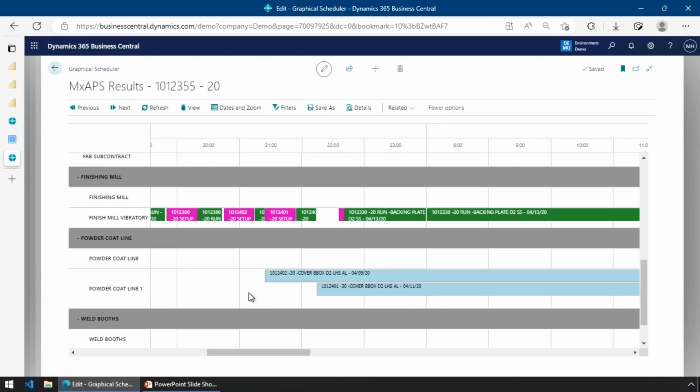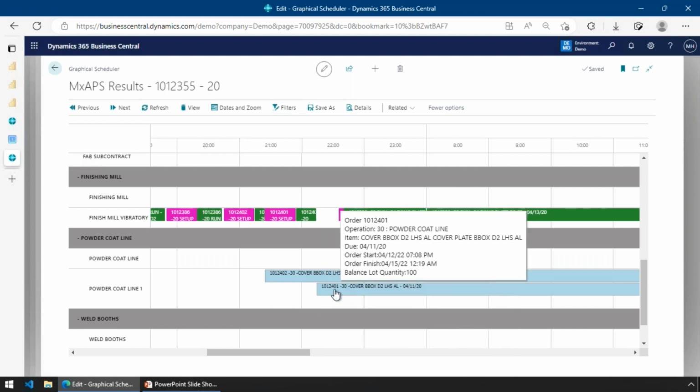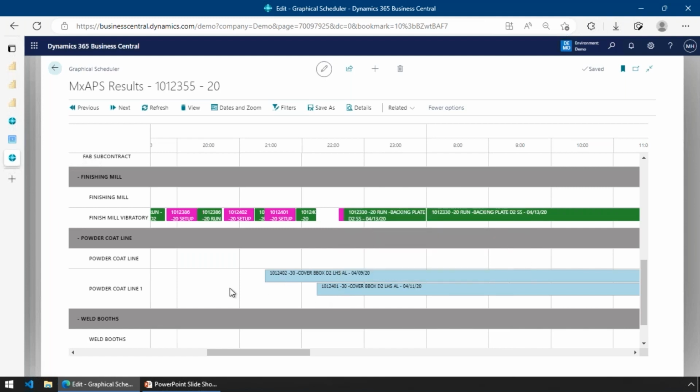And then you can say, well, what if it wasn't a bottleneck? What if I make that an infinite capacity machine? What's that going to look like to get my best schedule if that machine didn't have a bottleneck? And you can use that to analyze what you need to do in your environment to figure out how to improve your scheduling, or more importantly, how to improve your throughput, right? In this case, it means, hey, I need two of these machines, or maybe this is just labor. I need two people on this instead of one person, depending on what that machine requires, okay? So it allows you to figure out what your bottlenecks are and come up with ways of identifying how to correct those bottlenecks, or just do subcontracting like this guy is.